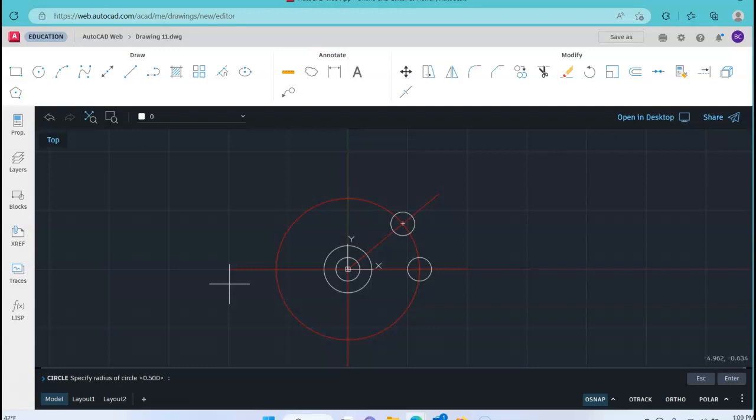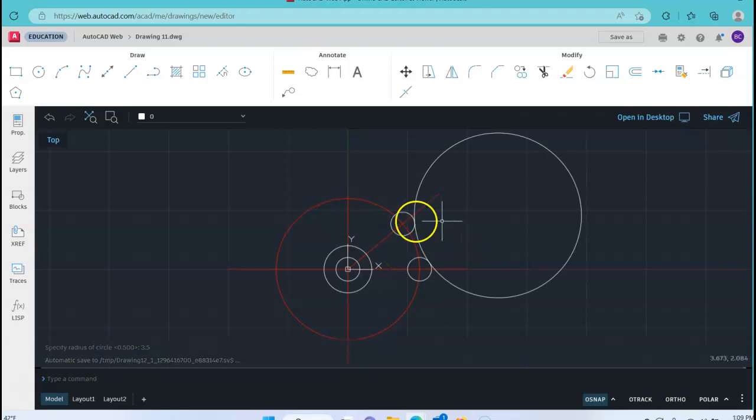Well, if we have a 3-inch radius from center here, so from here to here was 3 inches, and we're going to the outside. Well, we didn't do the outside. We're going from here to here, and that is the 1/2 inch radius from there. So we've got to add a 1/2 inch to the 3. So our radius here is going to be 3.5. Okay, now notice it places it going that direction.